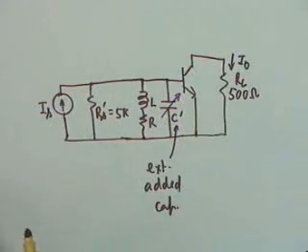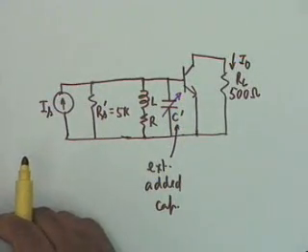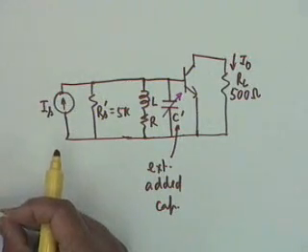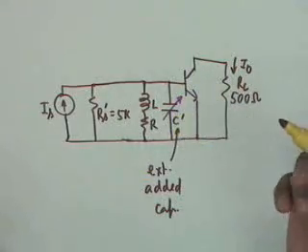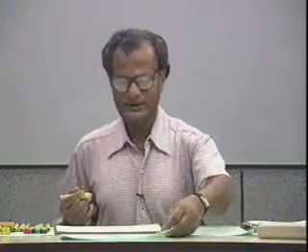Of course, for tuning, you have to keep C prime as a part of it, at least variable. As you know, air variable capacitors have a range of a few pF to, what is the maximum? 500 pF, actually 478 or something. This is the air variable capacitor. So if this lies within that, you can use an air variable capacitor and tune it. If it is more than that, then you use a fixed capacitor in parallel with an air variable capacitor. We will see how.